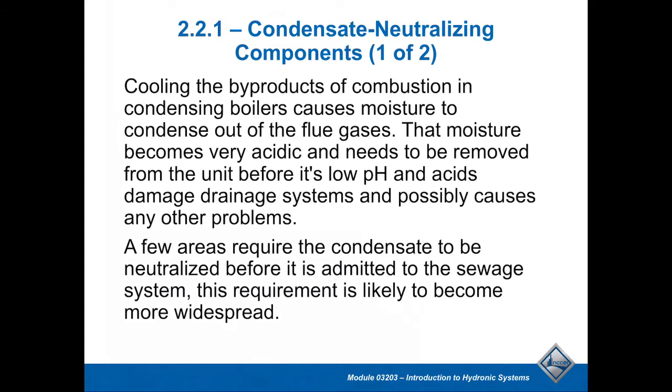Now, in situations where we run into a condensing environment, we have to be aware that in some applications you may have to concern yourself with the acidic nature of the condensate and where that's going to go. With the low pH, it's generally more acidic.